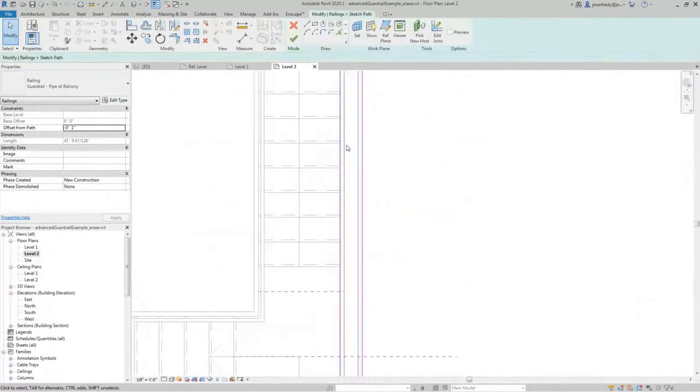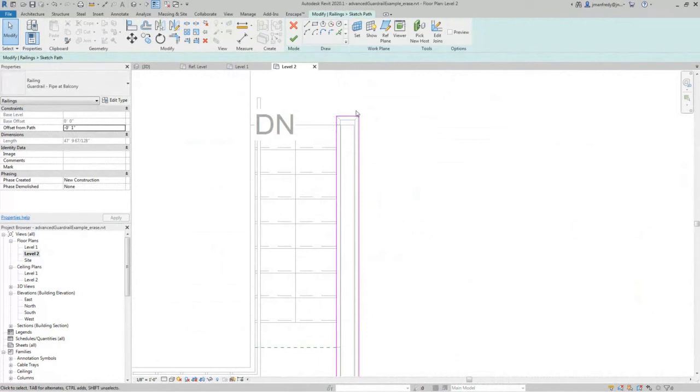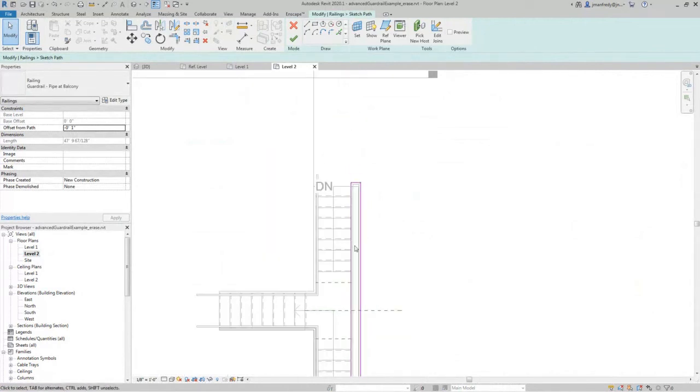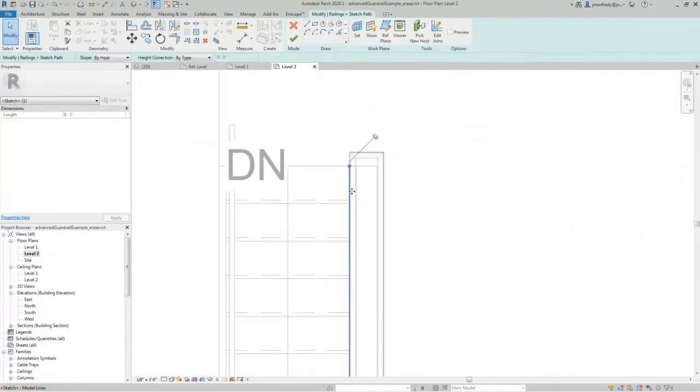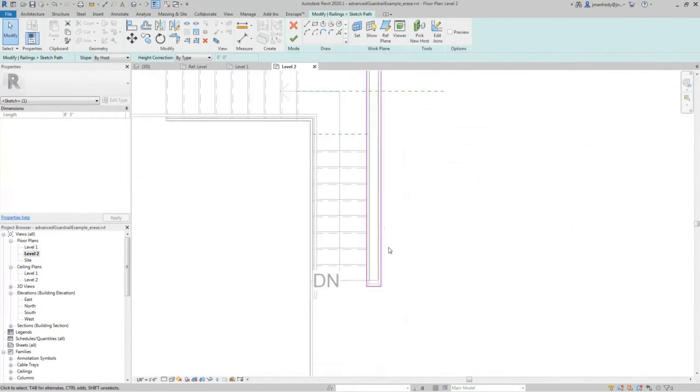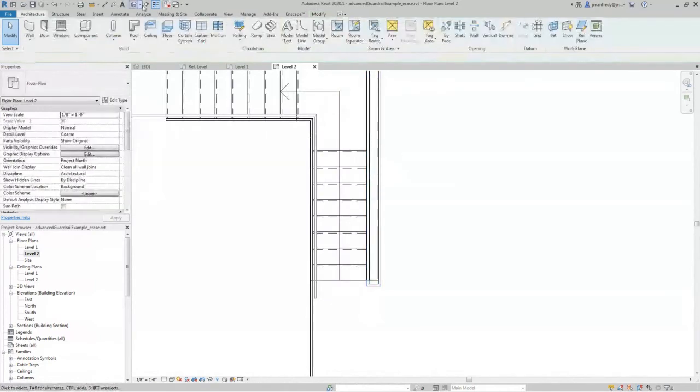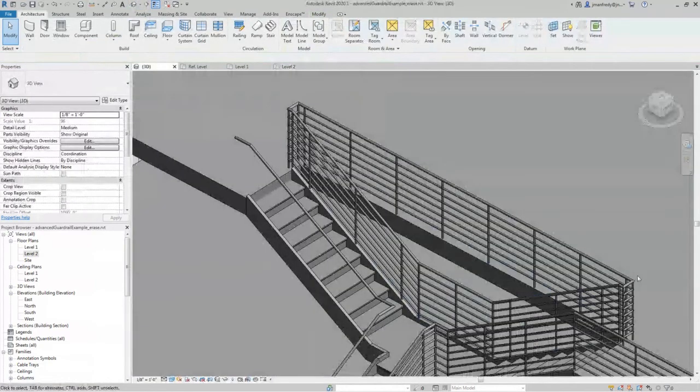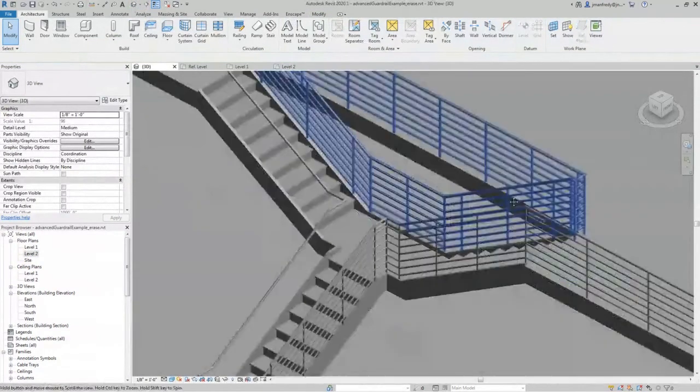See? It's a loop. It goes all the way up, and you draw the rest of it all the way around. You take what Revit gives you, which is typically up to here, and use the line command. You just draw the rest yourself. Just piggyback on the end of that line and keep going, and draw the rest of that path that loops back to where Revit ended the railing. And so now it continues one big circuit right there.